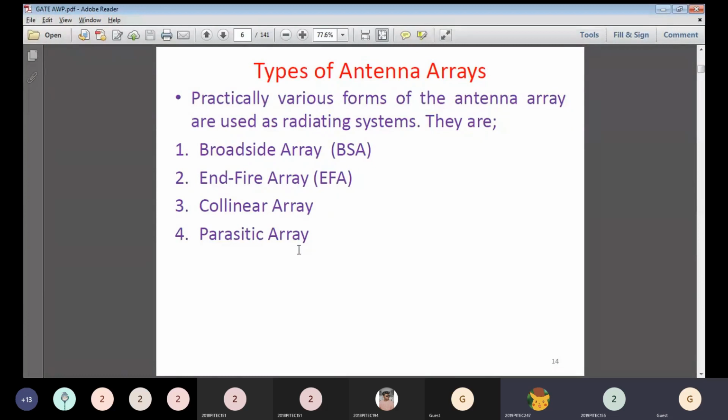Apart from that, we also discussed what a dipole is and how the dipole antenna radiates energy in the form of EM waves, and also the monopole. Monopole is like our dipole antenna, but it won't have the opposite pole. In the opposite side, we place the ground. In dipole and monopole, you have to concentrate on the field parameters: directivity, gain, effective aperture, everything. You have to know the formulas, and later you should know the monopole formula also.